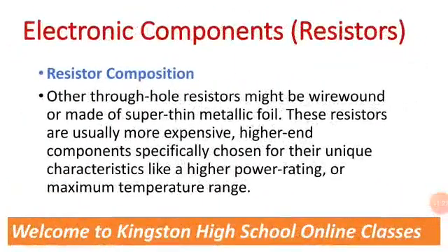Now, we also have other through-hole resistors. Through-hole is the one that you pierce through your motherboard, and then it comes out to the back of it. They might be wire wound or made of super thin metallic foil. These resistors are usually more expensive. They are high-end components specifically chosen for their unique characteristics, such as higher power rating. They have the ability to stand a higher power or higher voltage, or maximum temperature range. I believe you understand that.